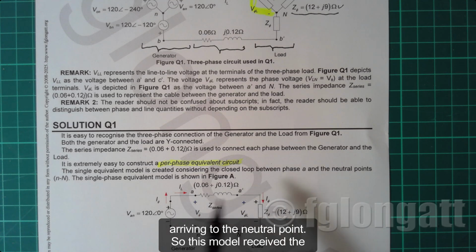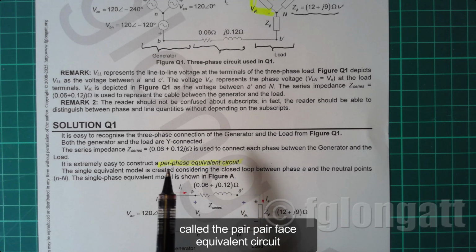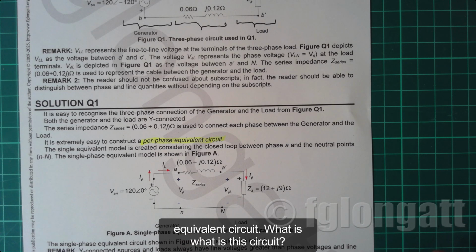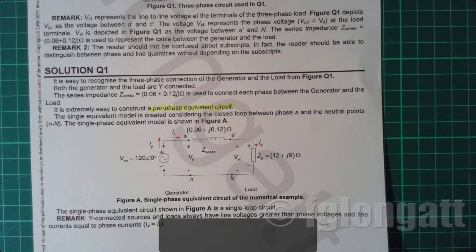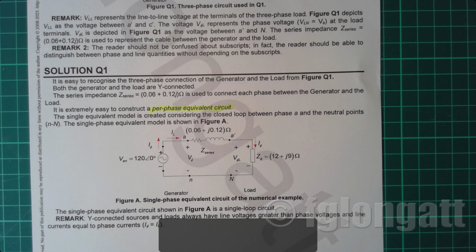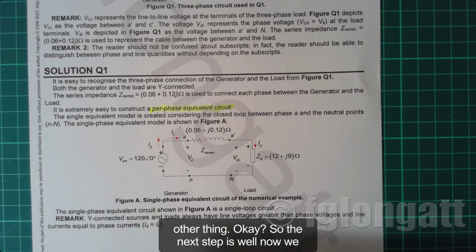This model is very useful, and it is called the per phase equivalent circuit. Also some books, and I prefer this name, call it the single phase equivalent circuit. What is this circuit? Well, this circuit over here is the representation of one of the phases inside the three-phase system. And we can do that because there is something that is called three-phase symmetry. So working out the solution of this problem in one of the phases will give me the results to calculate the other phases, okay?